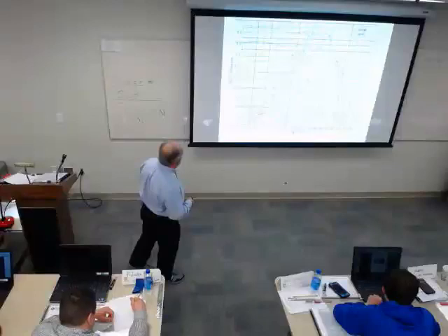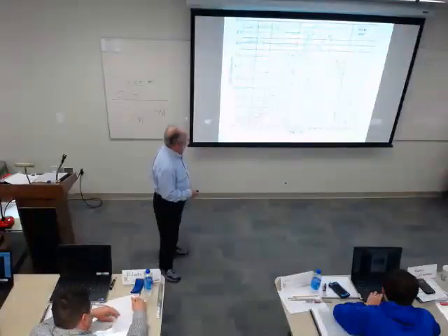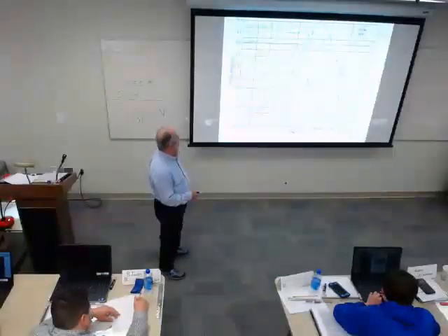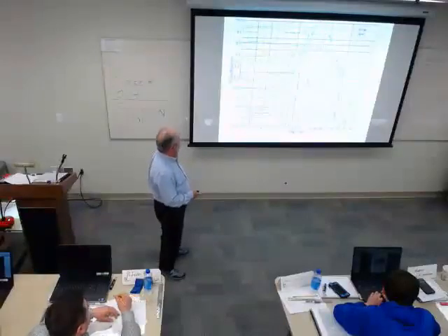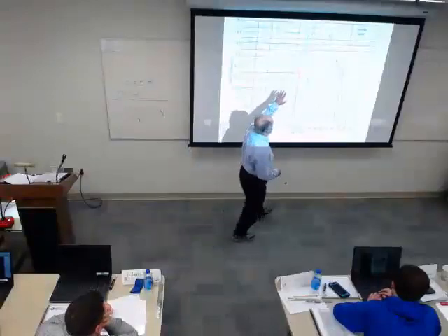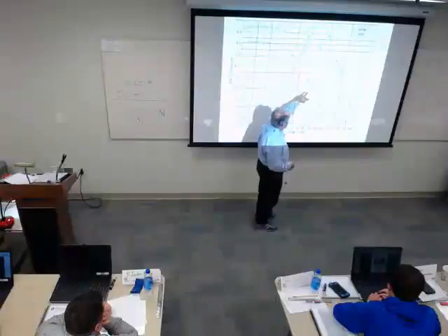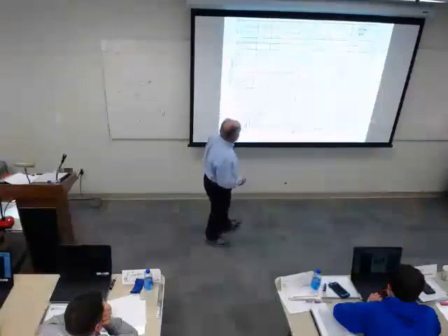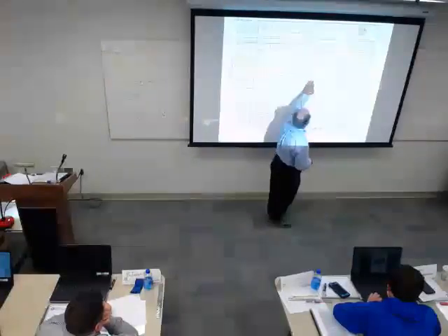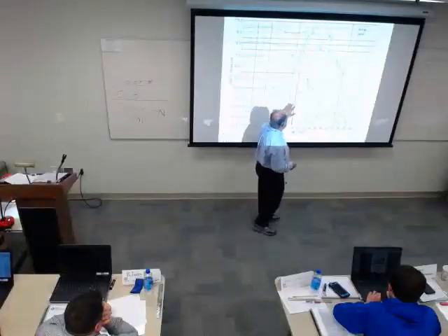All right, so looking at our curves here, 18,000 CFM, and we're looking at 5.75 inches, or 5.5, I think it was. And yeah, it was. There's our intersection, and we can see we're kind of close to the curve, but not too bad. We're down at least on that part of this curve right here, 1073. So 1073 is not a bad selection. If we went to this one over here, you can see that if we slowed that one down, well, it's just not a good match. So our best match happens to be this one.